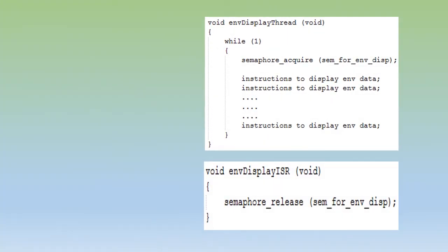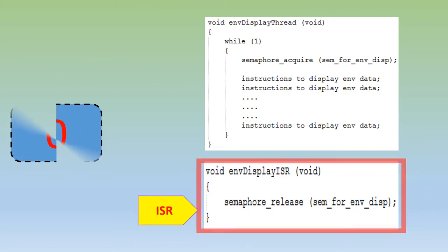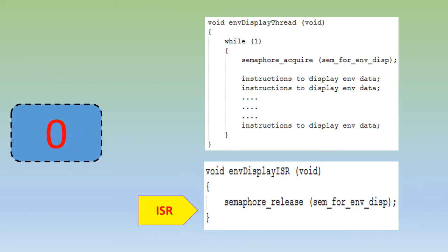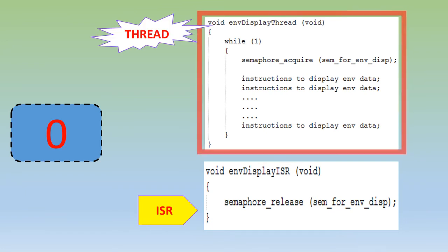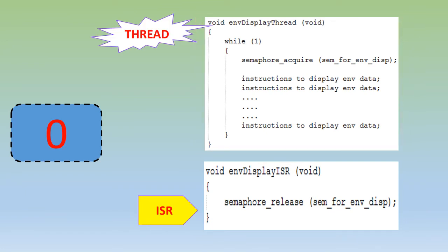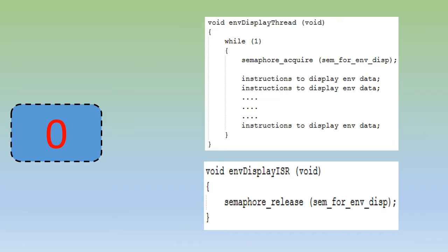This is the body of the interrupt service routine, which gets called when an interrupt is triggered, and this is the body of the thread. This thread enters execution in an infinite while loop. First, it acquires the non-mutex binary semaphore, and note that we created this semaphore with its initial state as not available in the main thread.